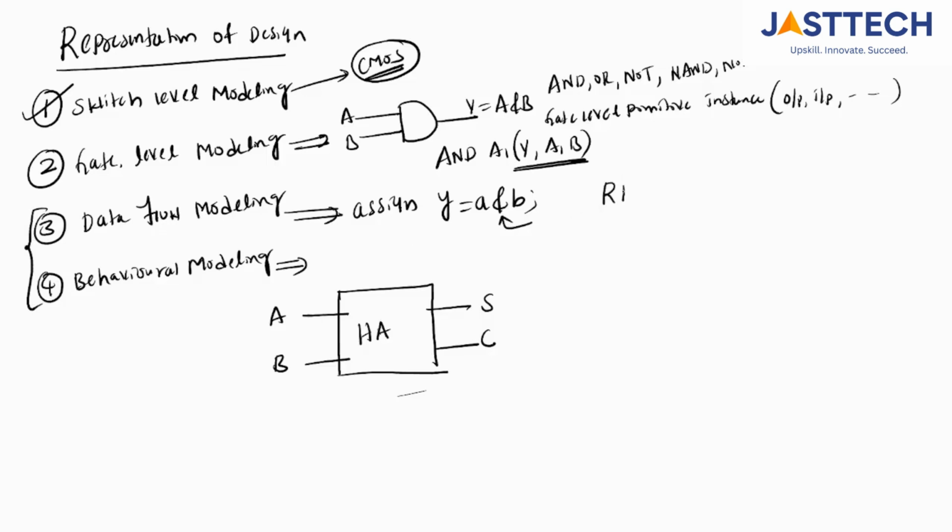So mainly that is RTL. RTL is nothing but register transfer level. It shows how the data is transmitted through the registers, and inside it will be converted in terms of D flip flops. So when you write the RTL code, this RTL will be converted into a gate level netlist.